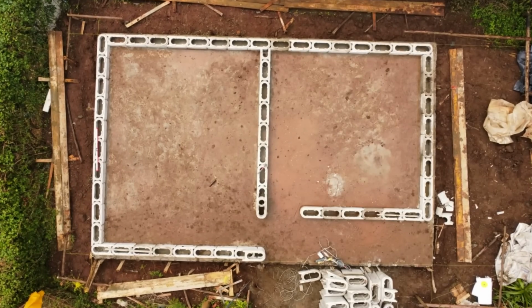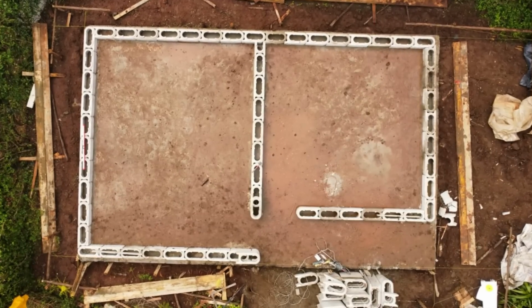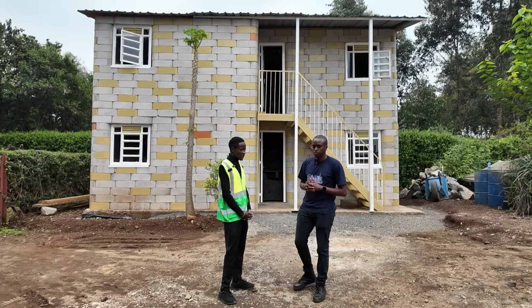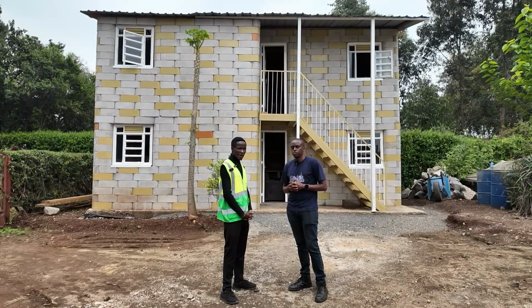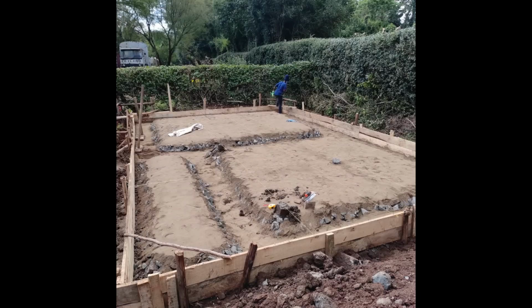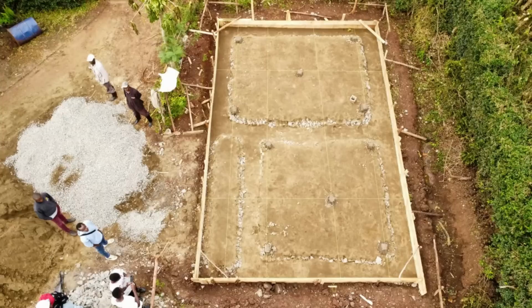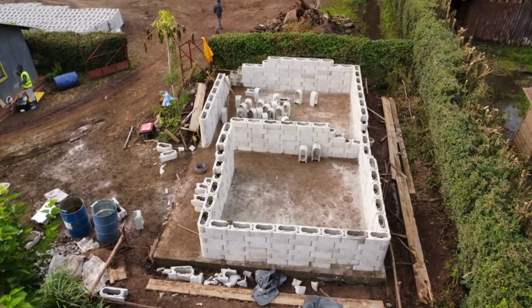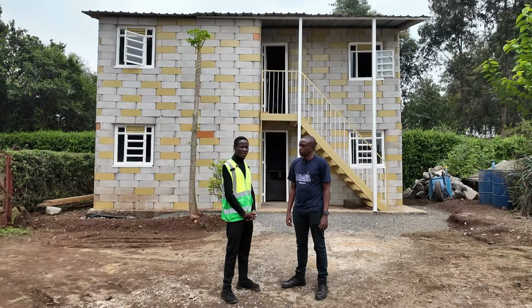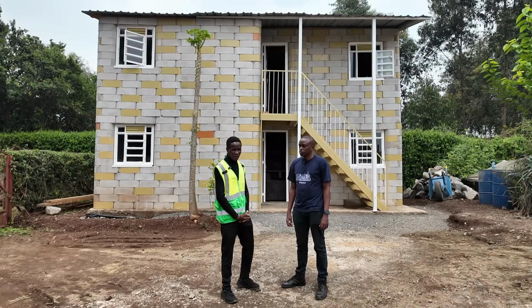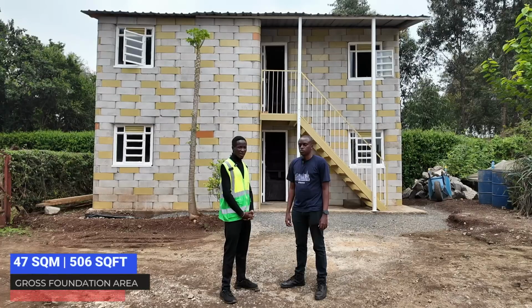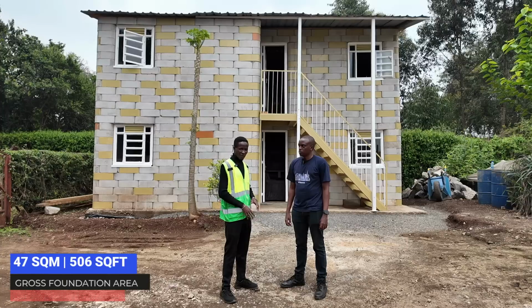How do you do the integration of the twist blocks from the foundation? Well, to begin with, the foundation was a raft foundation where we had excavation, the trenches where we need the walls to pass. Then we did a hardcore packing into the foundation, and then we filled it with fine sand. Afterwards, we laid a DPM. That is just in a nutshell how we did the construction, and then eventually did the concrete casting of the foundation. The total floor area for the foundation was 47 square meters. That is the gross floor area for the raft itself.